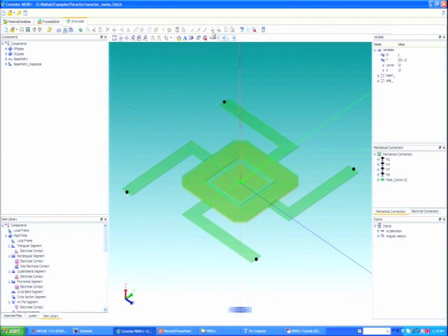One thing I didn't talk about earlier is the concept of exposing variables. Now I know it's not very clear in this projector, but some of these have a little E next to them. This is beam E, side E. E means exposed, meaning these variables are available downstream in Cadence or MATLAB as variables or parameters that can be changed. So I can go into Cadence and say, okay, beam change in Cadence or change in MATLAB. I do not need to come back into this tool. So this is the power of parameterization: I define it here and it's available for me downstream to modify as I see fit. Okay. Any questions here?